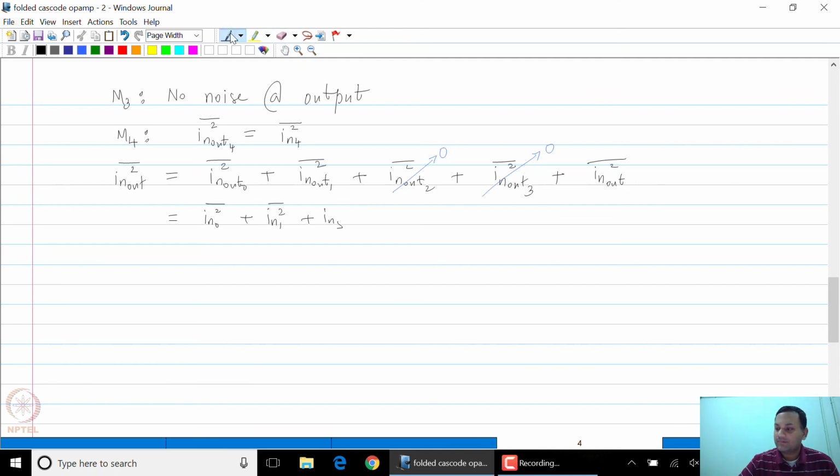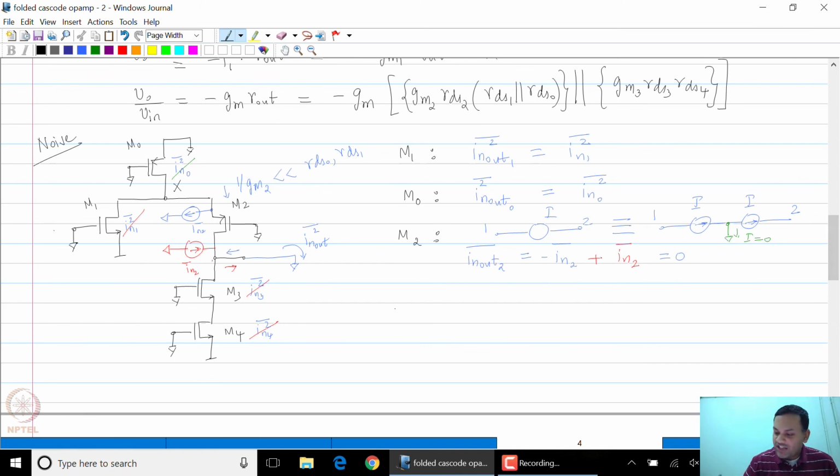I apologize. So there are 3 sources of noise. This is the short circuit noise. The input referred noise voltage, which I will now represent as EN squared, is nothing but the short circuit noise over the overall effective transconductance squared. The effective transconductance of this circuit is, of course, GM1.